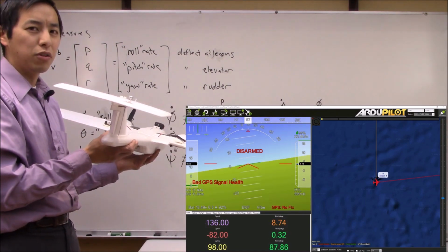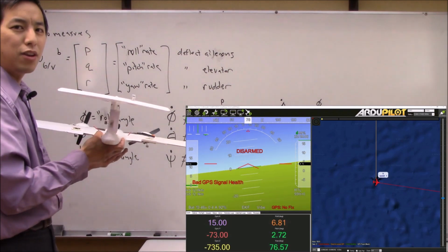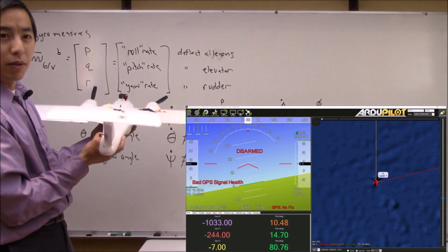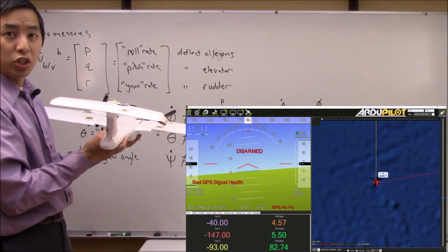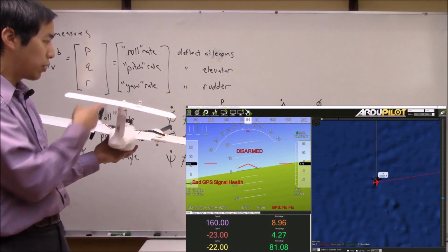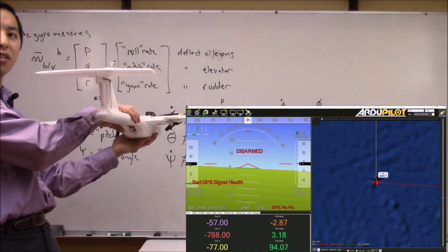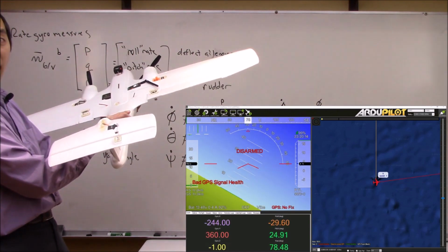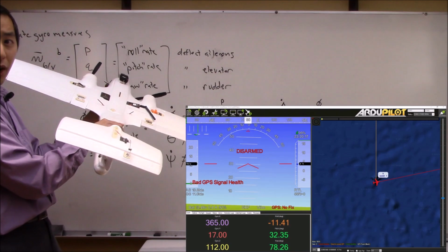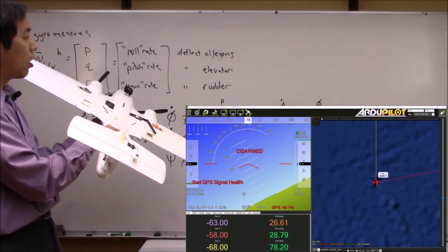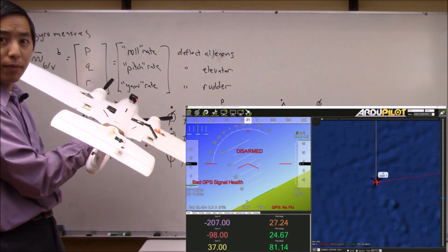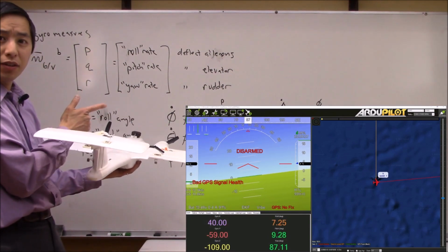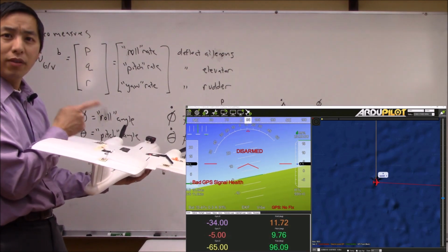So again, you see that there's this weird mismatch of nomenclature here. You might think that the gyros are basically being integrated to get roll, pitch, and yaw angles, but that is not true. It's actually going through a more complicated scheme, but this is kind of interesting. So again, I can maneuver the aircraft around, and it is making measurements from its rate gyros, and it is using that along with this function that we're going to be talking about to compute Euler angles. So that's our game plan for today. I want to talk about how that computation is done.